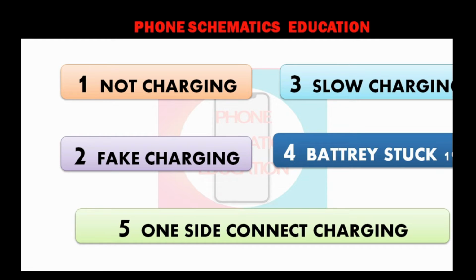In this video I will talk about a little advanced level diagnosis. If you face any problem mentioned for charging related issues, first you should try the normal, basic tasks. First clean the charging port, obviously change the charging flex. If you doubt, replace it with a new battery.